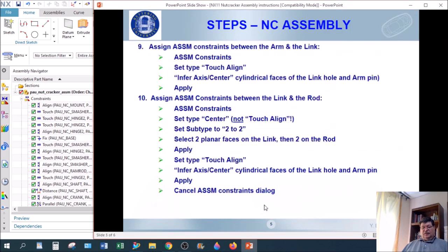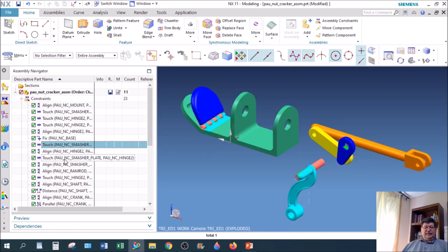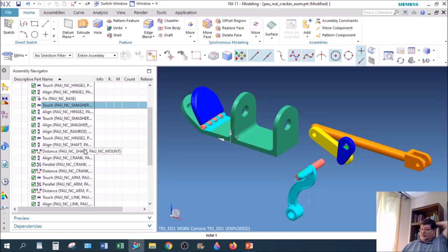You can use your directions here to finish the part, or just follow the video, or try it yourself, your choice. You'll learn any way to do it. But editing the constraints is the tough part. If you get something in conflict with one another, there's different ways you can do it. It's kind of hard to show you how to troubleshoot without having an error. But if you had 4 parts that were in conflict with one another, you can try suppressing one of those that has a red X on it, and whichever one you suppress that fixes all the constraints, all the red X's, the conflicts go away, that's the one that you probably want to delete and then recreate to fix it.